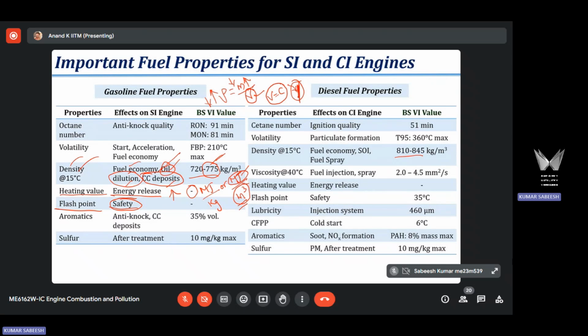Gasoline and diesel are generally very safe. We already discussed that. Gasoline flashpoint temperature is negative, diesel is positive, well above ambient temperature. So diesel will form a very lean mixture which cannot ignite. Gasoline will form a very rich fuel-air mixture which cannot ignite. So both are safe fuels and there is no flashpoint temperature regulated by the standards.